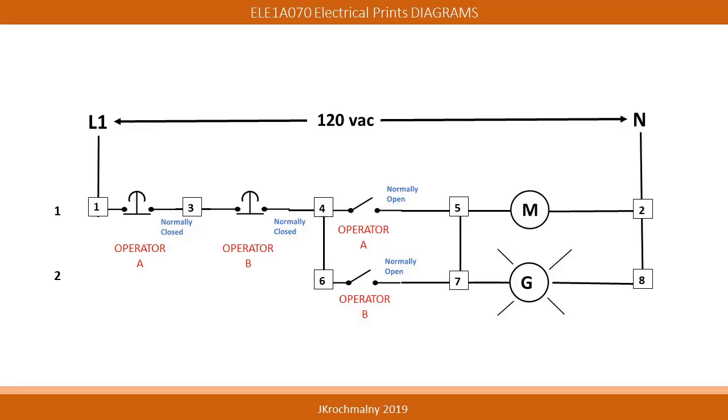Ladder diagrams will have terminal blocks that conductors will be wired to. There will be generally 2 terminal blocks used across each electrical device. Jumper wires can be used to connect certain terminal blocks together. Technicians can use these terminal blocks for measurements using multimeters. Here is the finished ladder diagram created for our sample sequence of operation.